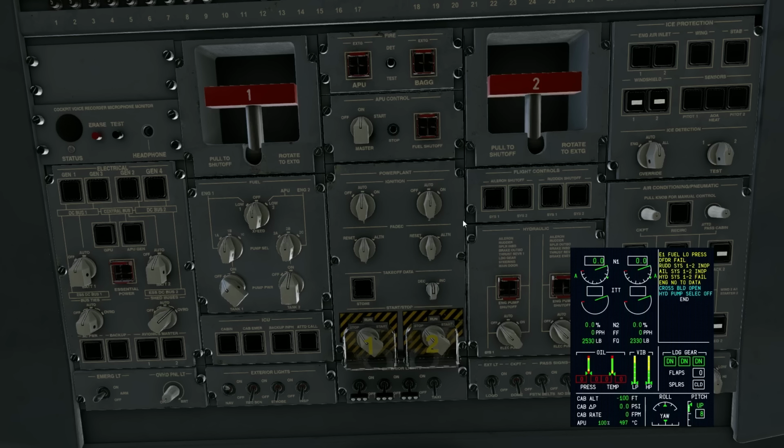Coming down to our ignitions here. So these are the controllers for the ignition to the engine. We have a 3-position off, auto, and on. Off does what it sounds like. No ignition signal will be sent to the FADEC, so the FADEC will not command ignition during a start. It also will not send any fuel. So that is, for example, if you have to motor the engine.